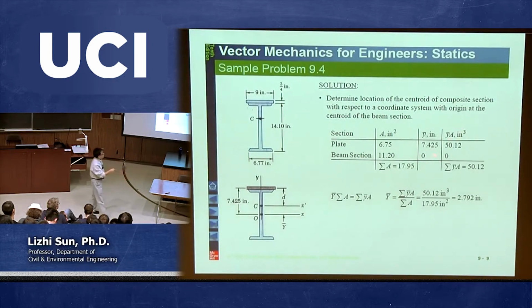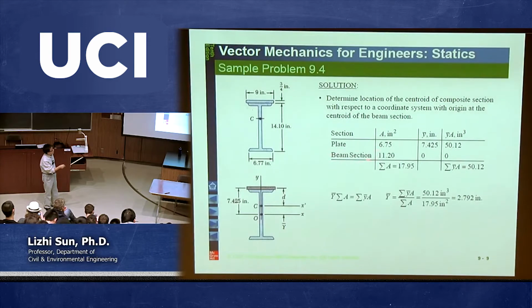Okay, going back to look at this picture. Keep in mind this second row, I'm talking of the local y bar, that's called the lowercase y bar, with respect to the second geometry, this W14 by 38. Now, for this one, we are picking x and y passing through the centroid or the center point of this second part.